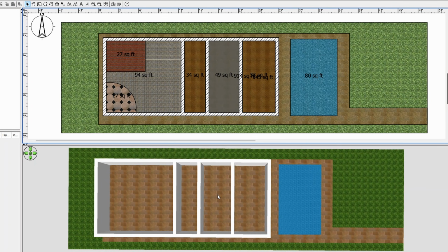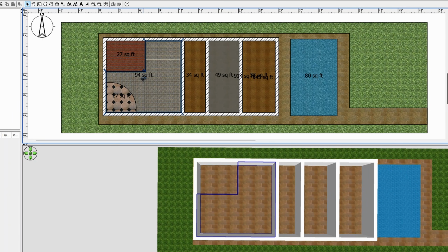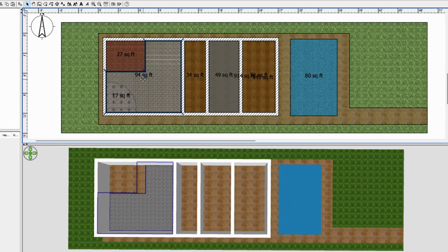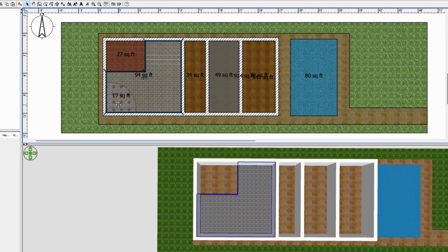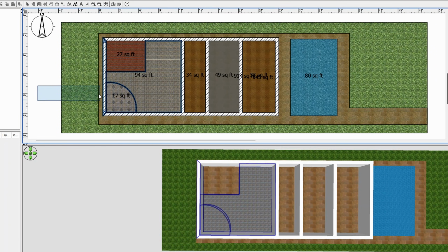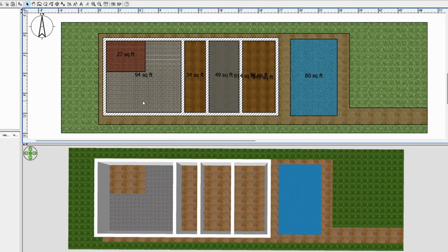When several floors occupy the same elevation, they overlap each other. Not in the 3D view. In the 3D view, the edges become visible. If you want to move a floor to the top, just select it, cut it, and paste it. If you can't select the floor, just select all and deselect the other floors and walls. Then cut it and paste it again.